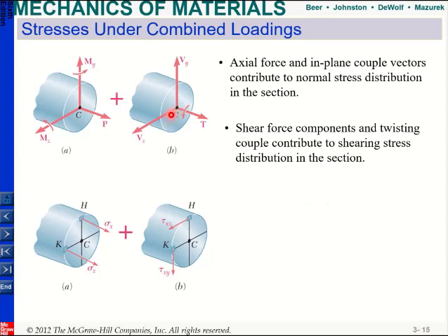Okay, for example, in this case, if you look at Vy, your shear stress at K due to this Vy will be going upward, but your shear stress due to torsion might go downward. So it's important that you look at the direction of each force, as well as torsion, and determine the direction of your shear stresses. You might need to add them up, or subtract them, and you might need to do other things. So it's very important.